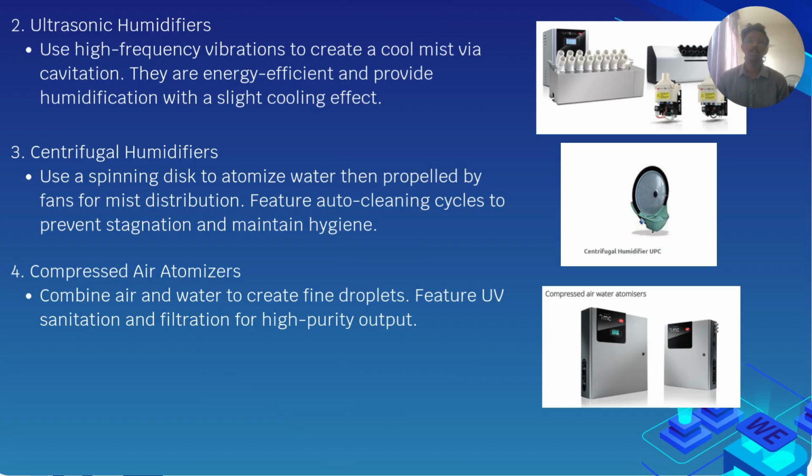So, moving on to the next slide, we will look at other advanced humidification technologies. First, ultrasonic humidifiers use high frequency vibrations to break water into fine cool mist through cavitation. They are very energy efficient and also provide a slight cooling effect, making them suitable for indoor environments.